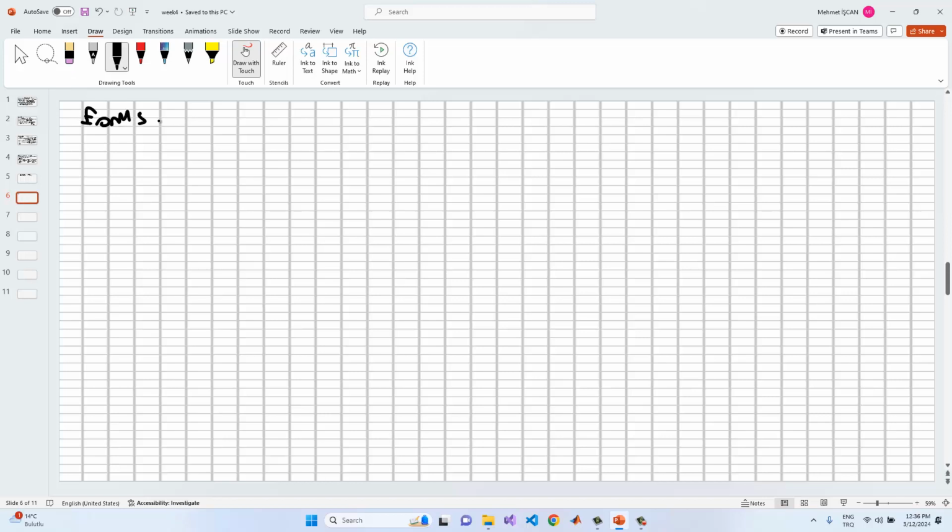Firstly, we have the first equation: m1 x1 double dot is equal to what? k2 (x2 minus x1) plus c2 (x2 dot minus x1 dot) minus k1 x1 minus c1 x1 dot.